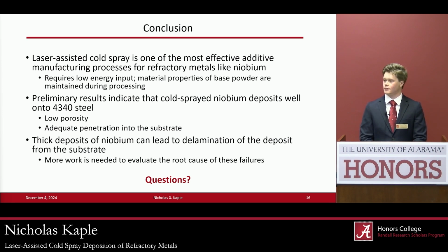Are there any other ways to create parts with cold spray besides spraying a pad onto a metal bar? Yeah, one way you could do that, that's also being used more and more now, is you can create tubes by essentially spraying onto an aluminum bar, and then you can dissolve away the aluminum. So using oxide dispersion strengthened steels, like I said, that has a nuclear reactor application. And so you can create tubing essentially by using the cold spray process.